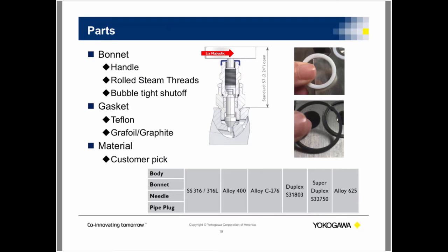Here's another question. It says, on oxygen cleaned services, are the manifold and transmitter assembled and tested for shipment? You can. They're handled with gloves. It's just a different type of test. You would have to do a different type of test to ensure that you don't mess up that oxygen clean.